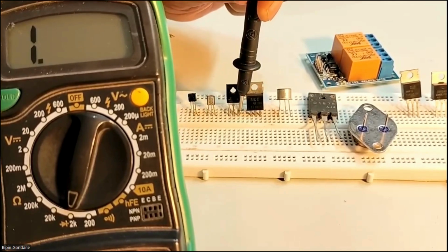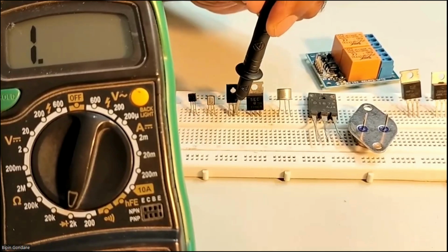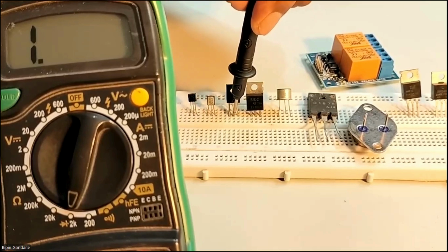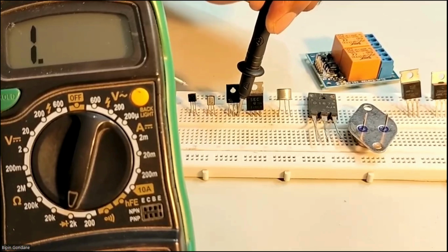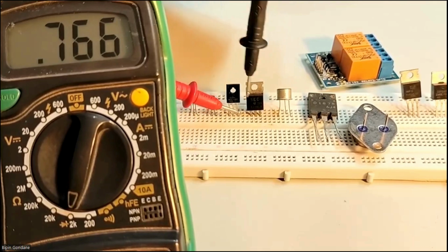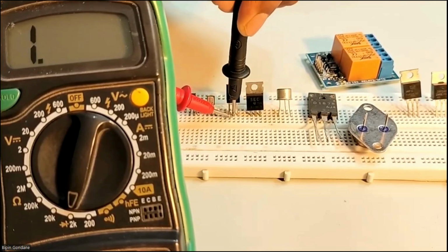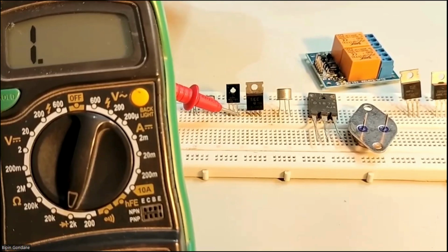These transistors are input transistors. This is BD140. So here the center will be, most of the time, the collector. The base will be on the side. So let's test this and check. I've got the value. Let's test this. I've got the value, right? So center and emitter and collector, I didn't get the value. So this is base, center is collector. Naturally, this side is emitter.